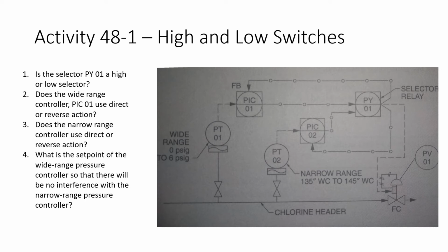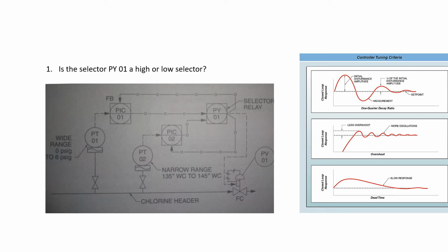And so why do we need a system like this? Since we didn't get to have a lecture this week, this should be kind of an example. Here would be PIC01, something like this. It has a big change, high gain, low integral. It's going to respond quickly. We want it to get up to pressure as quickly as we can. Overshoot should be okay because it's just compressed air in here.